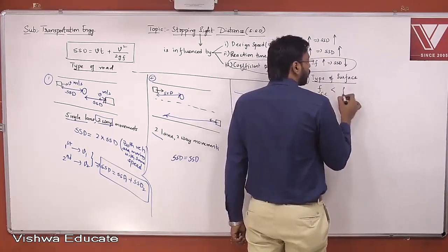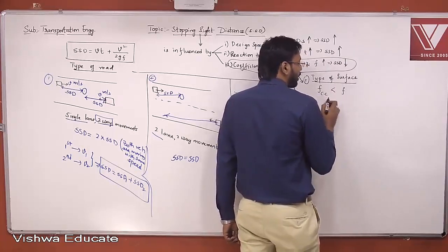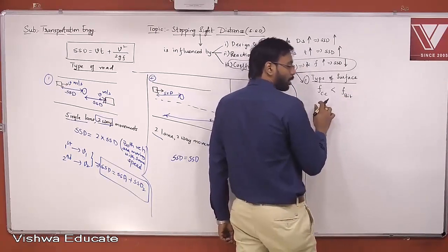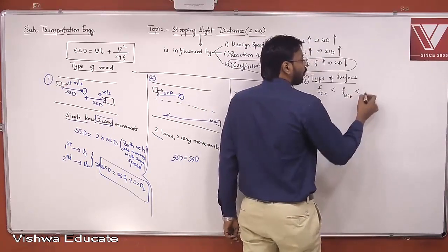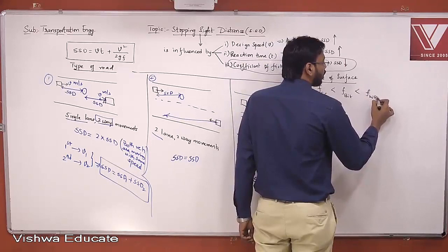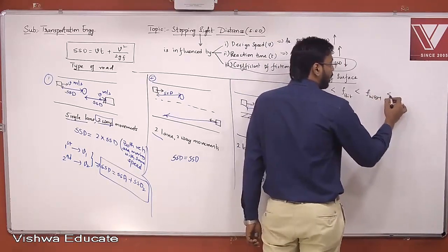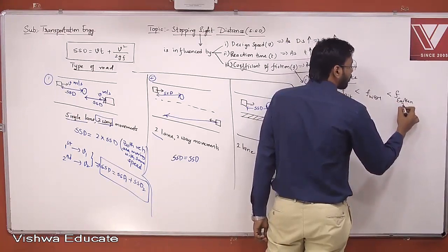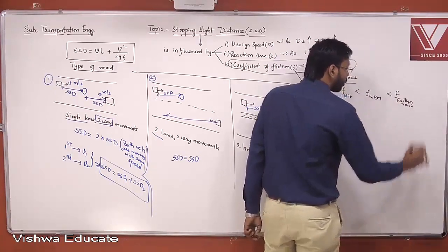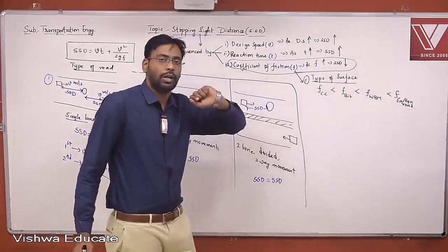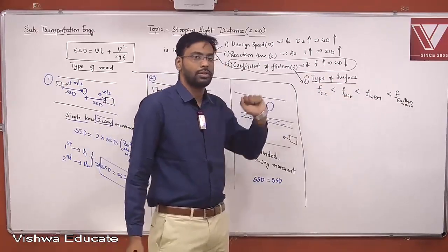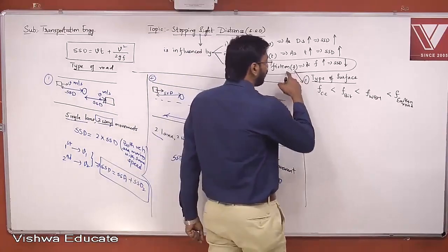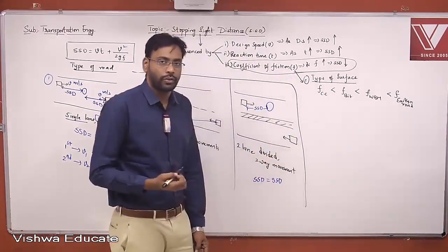Coefficient of bituminous is more than cement concrete, and coefficient of waterbound macadam road is more than bituminous road, and similarly the coefficient of earthen road. So for earthen road, the coefficient of friction is more, and for CC road, the coefficient of friction is lesser. So that's the first element which is influencing this coefficient of friction.